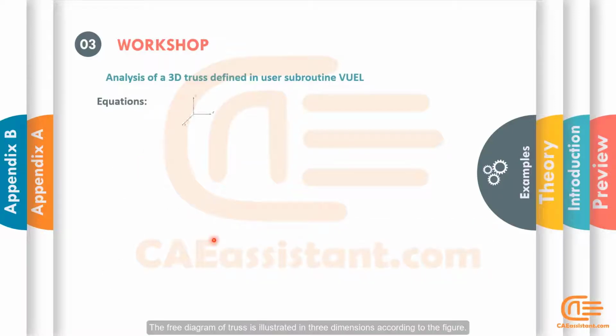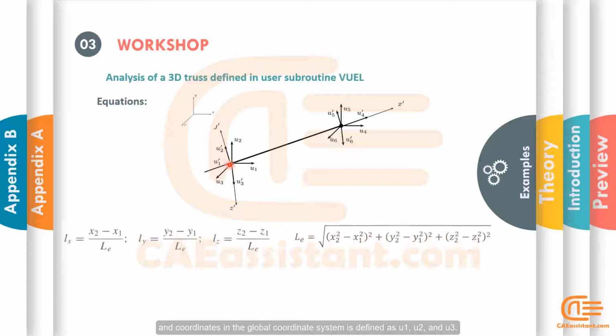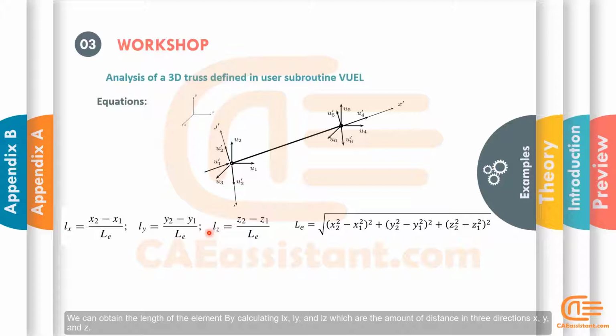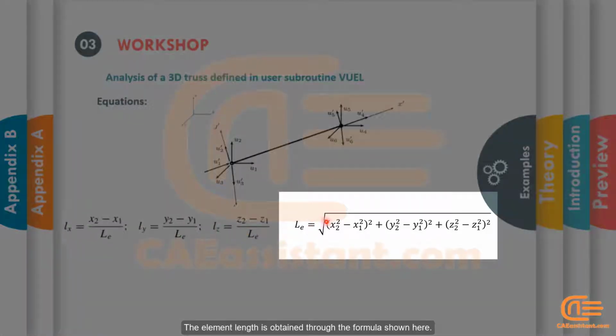The free diagram of truss is illustrated in 3 dimensions according to the figure. Its coordinate in the local coordinate system is determined as x prime, y prime, and z prime. And coordinates in the global coordinate system is defined as u1, u2, and u3. We can obtain the length of the element by calculating Lx, Ly, and Lz, which are the amount of distance in 3 directions x, y, and z. The element length is obtained through the formula shown here.